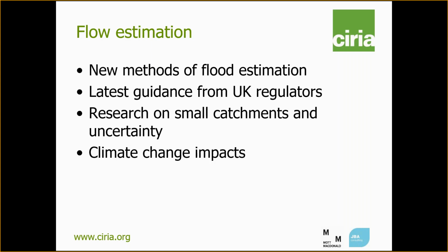The hydrology chapter has been updated, and that includes relevant new research and methods that have been developed since 2010. It includes the latest guidance from UK regulators and climate change guidance. So it includes new methods of flood estimation, including ReFH2 for design hydrograph estimation, driven by the FEH13 rainfall frequency statistics, and the methods for small catchments draw on research, such as applying FEH at a downstream location and scaling down on catchment area.